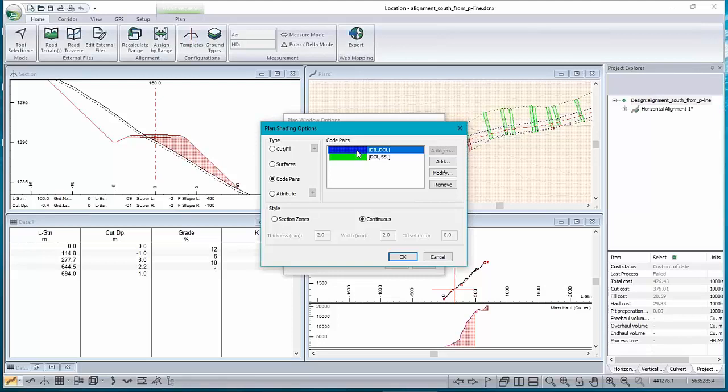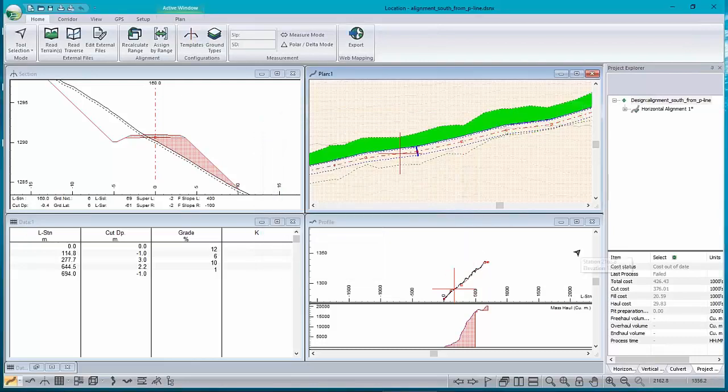Ditch inside left, ditch outside left. Yeah, okay, I set this up before. This one is going to show me the ditch on the left-hand side. This one is going to show me from the outside of ditch up to the slope stake. So it's basically your cut slope. And that's what it looks like.